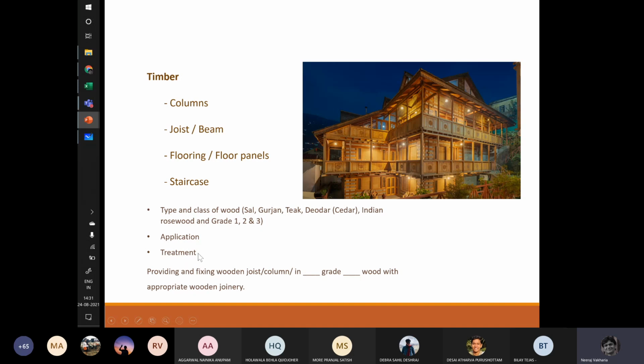And then the treatment. We might provide treatment, sometimes fireproof coating treatment, sometimes moisture proof treatment. Whatever we do with appropriate treatment, that also we have to add to complete its specification. This is for timber, the structural wood we are talking about, and not plywood and everything. If we are going to use engineered wood for beams and all, then we have to specify it differently. If some of you have that, then we can specify it particularly, because that would be unique. That is not a conventional or standard type of construction as of now.